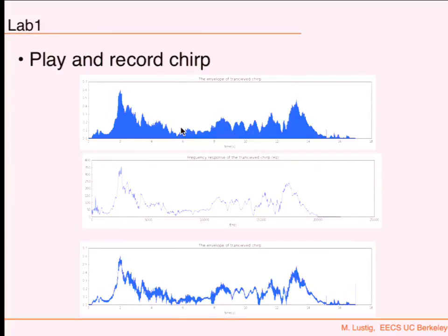Why is that? You basically look at the analytic function, which turns sines and cosines into e to the power, which have a unit amplitude. So this is one way to look at the envelope of the signal. There's a description in the lab of how to do this and why it actually works, and some mathematical derivation. But effectively, you can look at the envelope of this, and it looks exactly like the frequency, which is kind of cool.